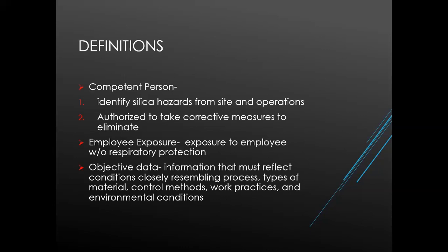All right, a few definitions. From the construction standard, a competent person is defined as someone who is able to identify existing and foreseeable respirable crystalline silica hazards in the workplace, and someone who has authorization to take prompt corrective measures to eliminate or minimize those hazards. Employee exposure means the exposure to airborne respirable crystalline silica that would occur if the employee were not using a respirator.